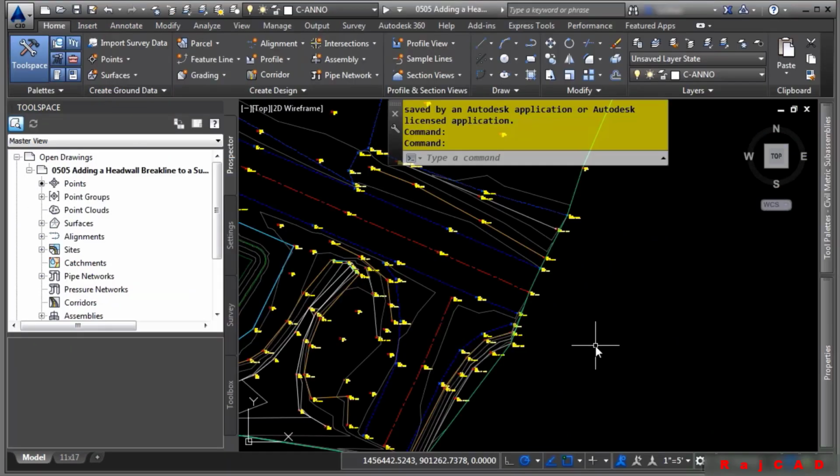Headwall breaklines are very useful when you only have either the top or bottom, northing, easting elevation of a feature, and either a consistent elevational difference between the points, or you've actually measured the distance at each vertex when you were in the field locating the objects. This depth would, in most cases, come from the surveyor's notes, of course.